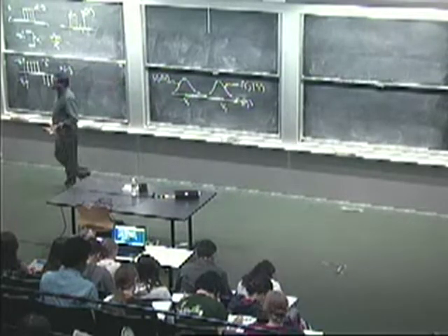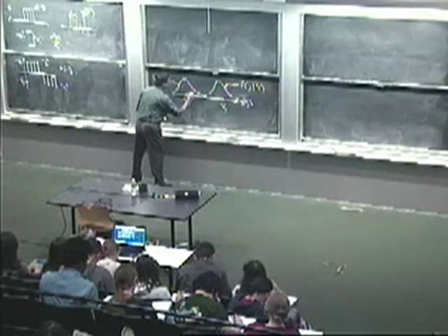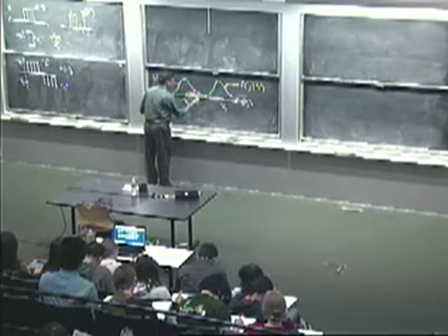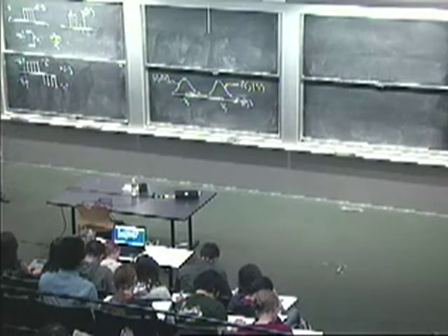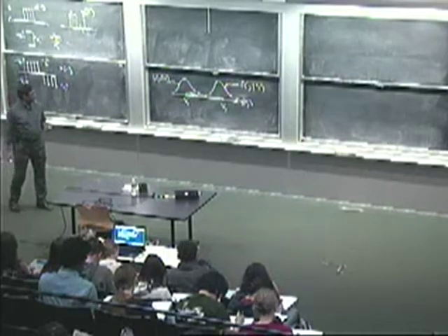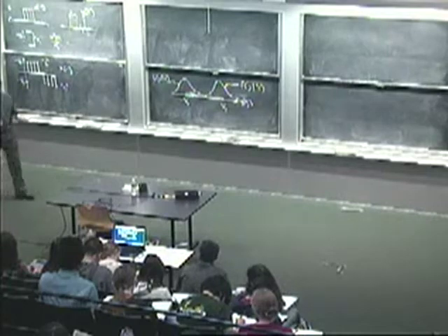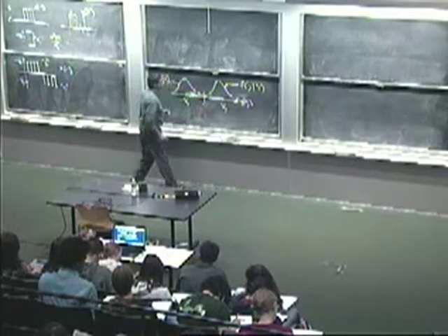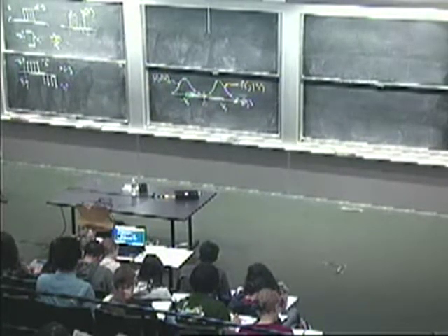And I've got to decide, did that come from having sent a 0 and getting this much noise, or did it come from sending a 1 and getting this much noise? Right? That's the problem. So if zeros and ones are equally likely, what do you think is a sensible rule here? Just pick a threshold where these two cross, right? Threshold in the middle. So if the sample is above the threshold, you declare a 1. If it's below the threshold, you declare a 0.